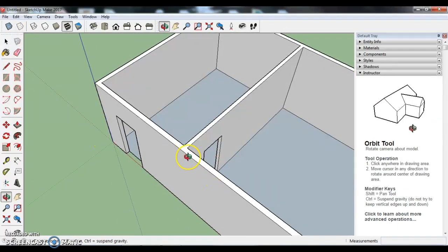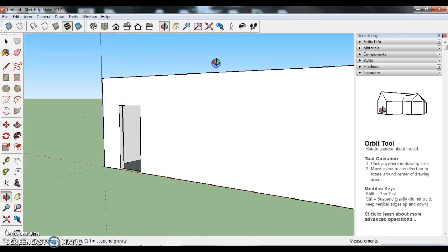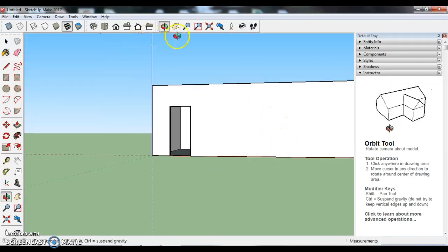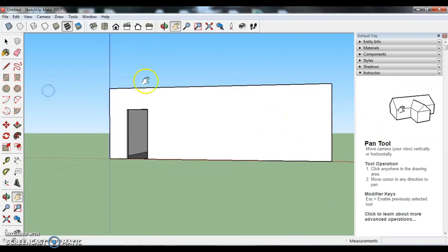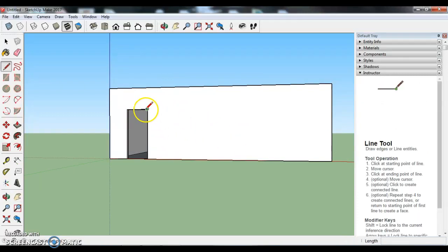I've got a door. Those look good. Let's add some windows next. Now, specifically, I want these windows to terminate at the same height as this door. So one way I could do that is use my line tool, start in this corner, and draw this parallel line all the way to the edge. I'll later delete that, but I have it here just in case.